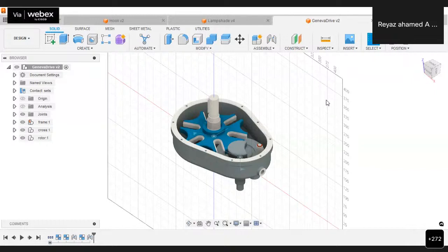While in the reverse engineering process, it is the opposite. We go for top-down assembly. That is, we create a component based upon the assembly. Design of jigs and fixtures is like that, because jigs and fixtures are holding components, right? So we have to create jigs and fixtures based on the component and based on the machine which is already available. We have to create the holding devices based on that. So we have to create a component based on the existing assembly. That comes under top-down assembly.